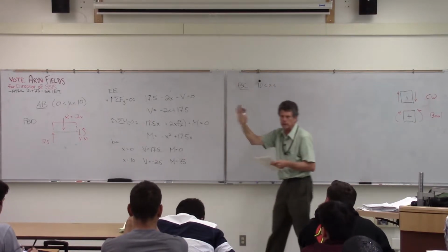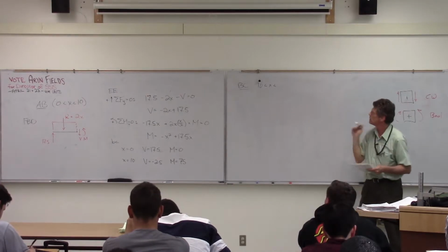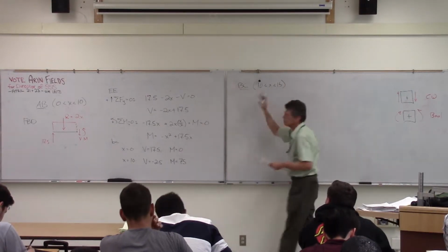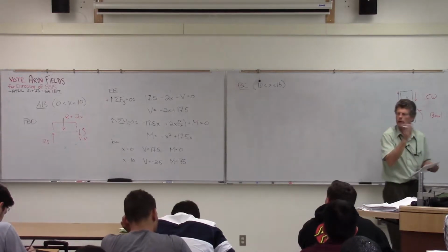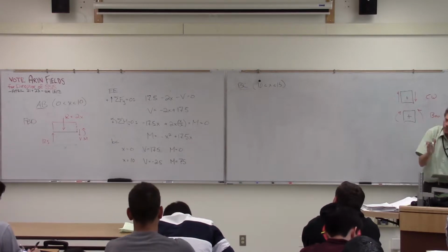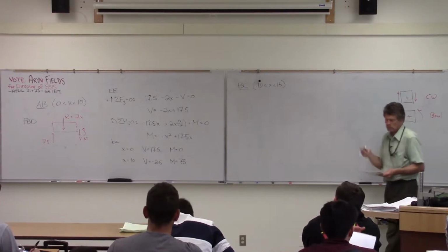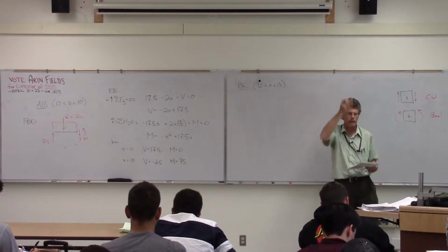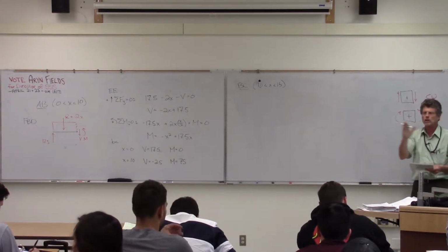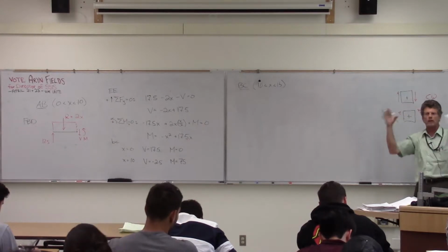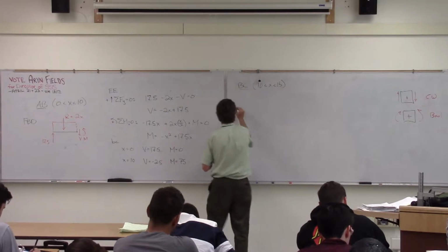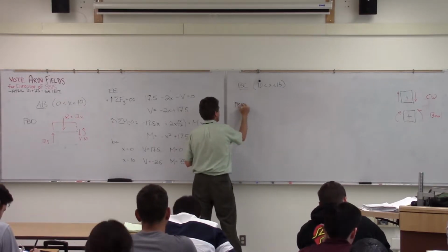From point B to point C is what I'm doing. And then I'm also putting the range here. So either one you can use, but I'm going to be making a cut now between B and C, because at B, things change. My uniform load disappears, and I see this new concentrated load show up. Nothing happens on that section until I get out to C, and then at C, all of a sudden, that concentrated twist shows up. So what I'm going to do is a free body diagram appropriate to that range.